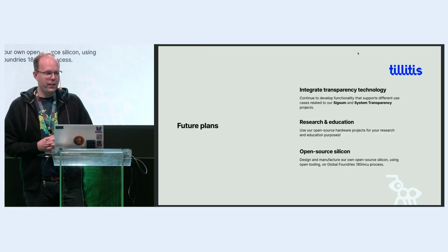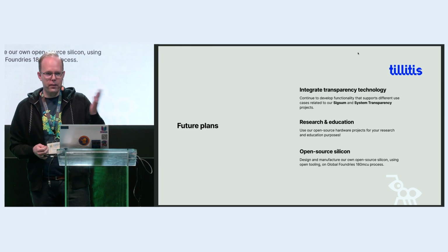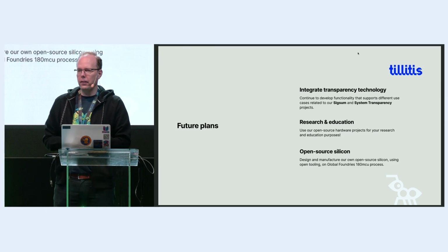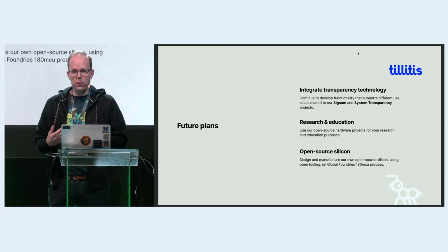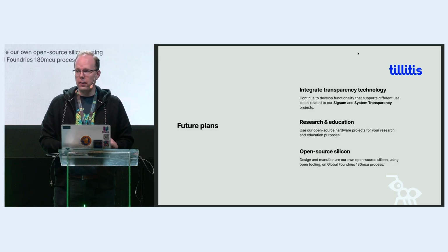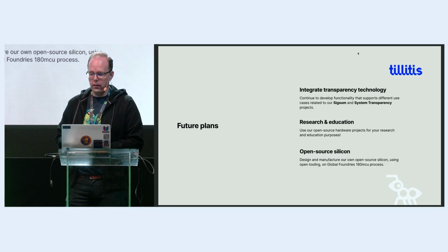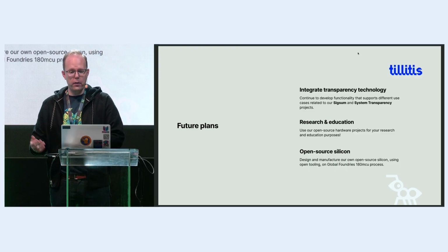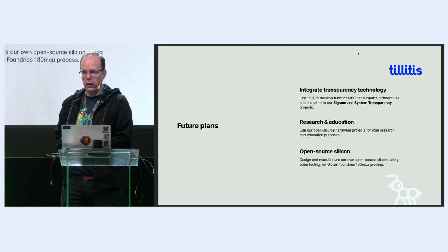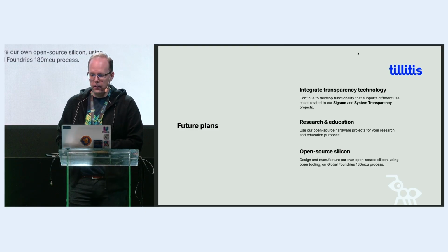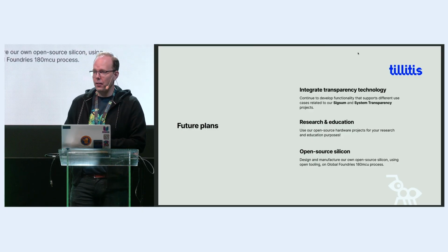The short version is that thanks to Google and Tim Ansell and Skywater and eFabless, there was a way to do open source silicon tapeouts using Tiny Tapeout, and you go through eFabless as an MPW service, and Skywater would provide you a tapeout. eFabless unfortunately shut down the company earlier this year, but now there's a new MPW service by Tim Ansell.